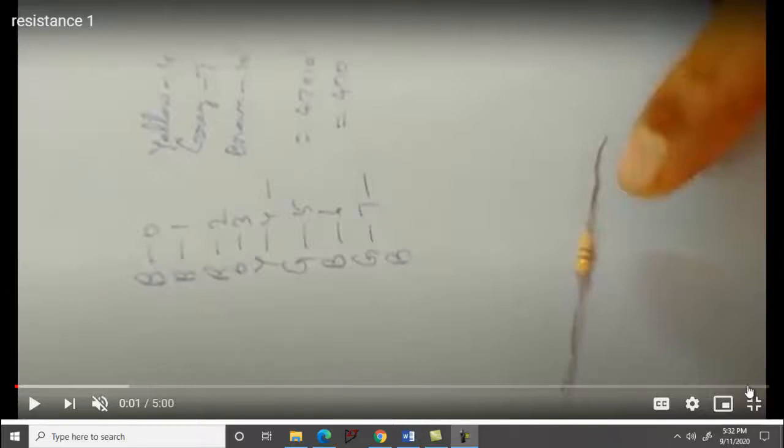Students, today we are going to verify the logic gate output, namely your AND gate with its truth table. We know the two input AND gate truth table. We have four logical combinations, namely 0 0, 0 1, 1 0 and 1 1. When these four logical combinations appear at the input of the AND gate, what will be the output? According to the truth table we know, but we are going to verify the truth table through an IC.